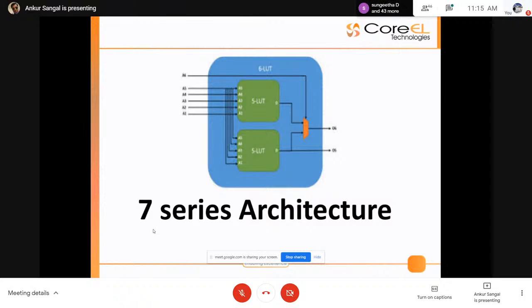Microcontrollers and microprocessors have some architecture, like a 32-bit ALU or 64-bit ALU, and different limitations related to the register bank and so on. But here everything is open. On the basis of your gates, you can decide. In the gates, you can see one name mentioned here, LUT. LUT stands for lookup table. With the help of this lookup table, you can implement any Boolean expression.